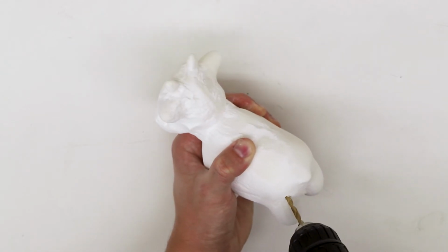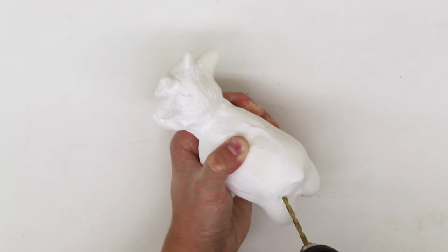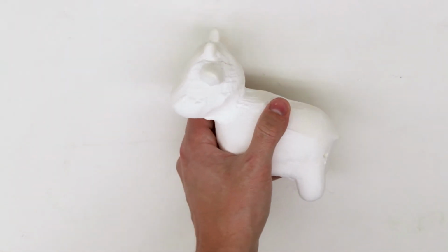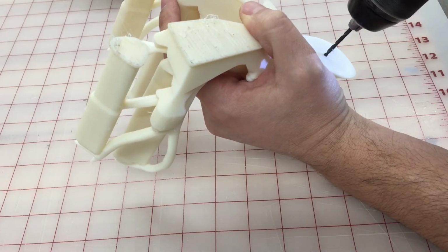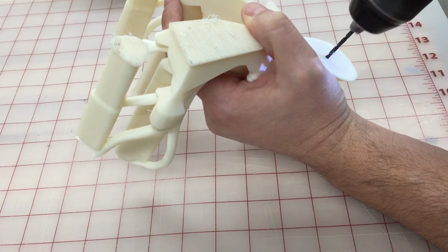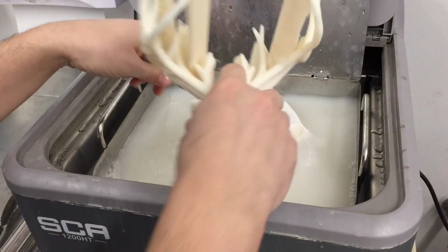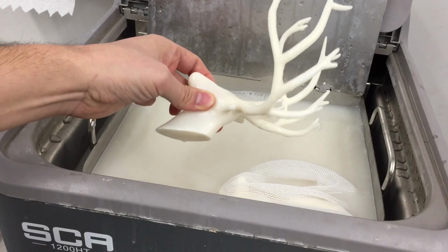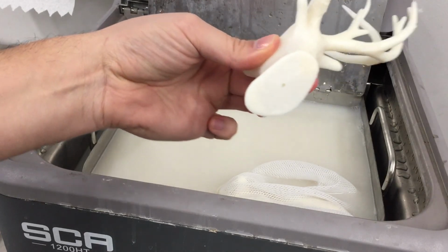As our method creates a single connected void inside the object, internal supports or excess material can be removed through a single access hole. For SLS or polyjet printing, a water jet can be used to clean excess material, while for more complex models, a 3D printing technology which allows soluble support material can provide a more practical solution. In either case, only a single access hole is required.